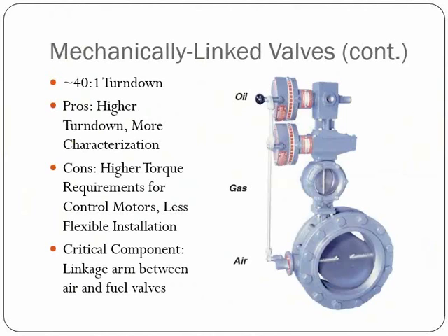Cons on this one would be that once you start adding more and more control valves and longer jack shafts, you'll have higher torque requirements for your control motor, so you may have to size those up to accommodate your torque requirements. And then I put on here less flexible installation.